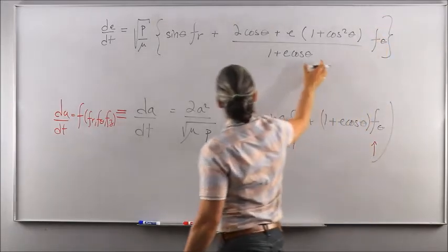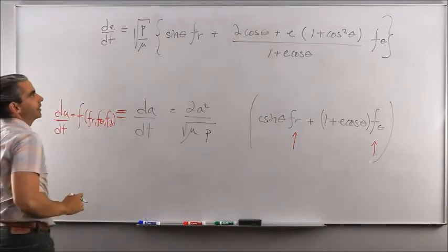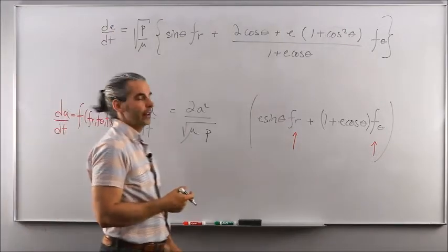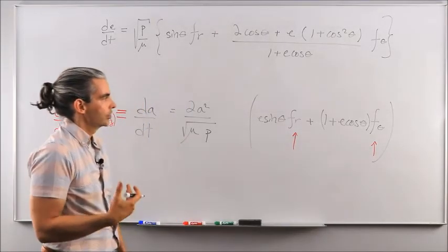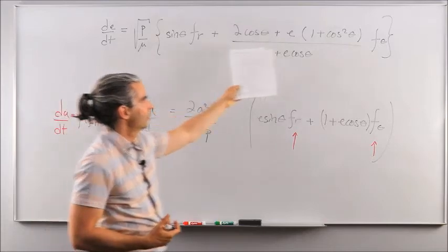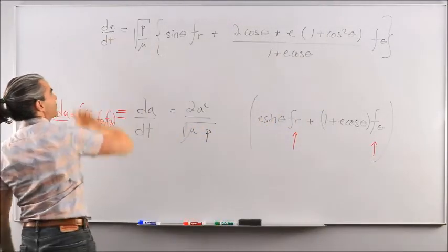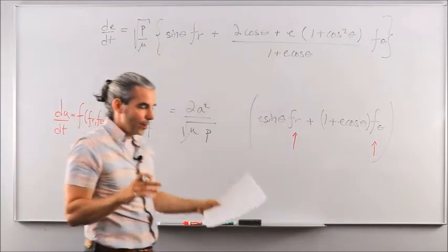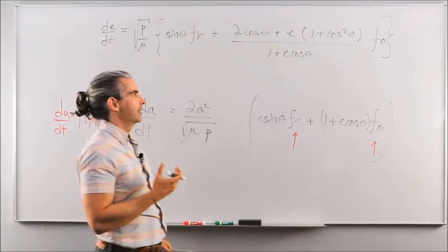So as you can see, the Gauss variational equation for the eccentricity is not a function, again, of the z component of the perturbing acceleration, which is f_z. Only the in-plane components of the perturbing acceleration have an impact on the eccentricity, which is the shape of the orbit within the orbital plane. So that makes kind of sense too, okay?